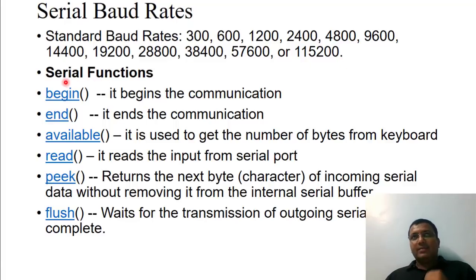So there are some standard serial functions available with the Arduino IDE. We'll see those standard serial functions. First function is begin. This function begins the communication. End. This function ends the communication. Available. It is used to get the number of bytes from the keyboard.